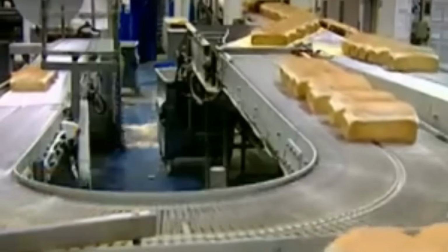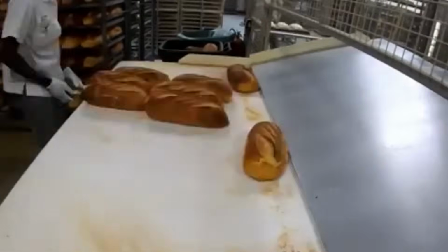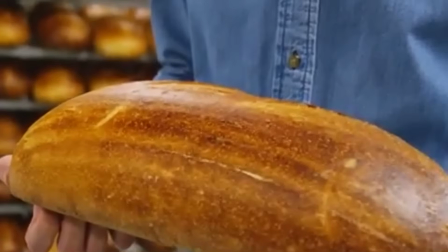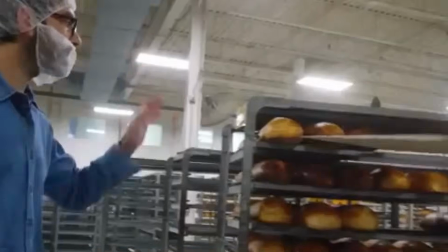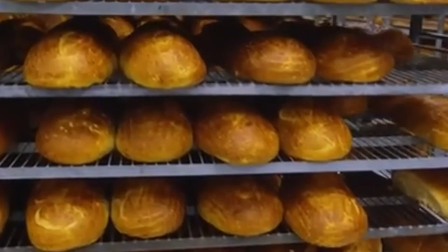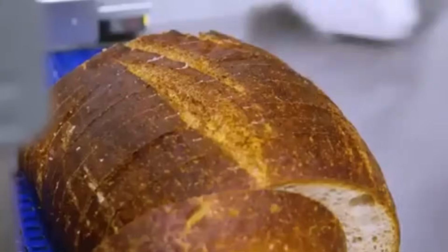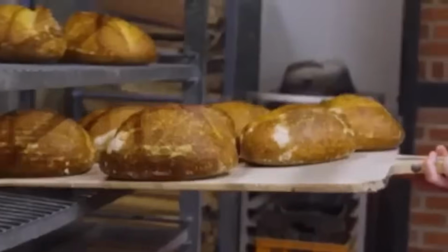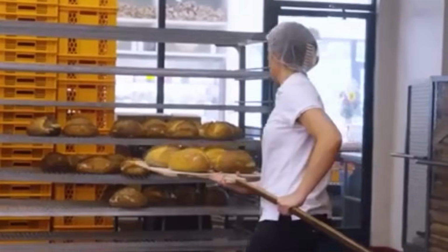Exiting the oven, the loaves are hot and fragrant, but far too fragile for packaging. They roll forward on the conveyor and enter a spiral cooling system, a towering structure of coiled belts that winds upward, allowing the loaves to circulate through cooler air over the course of 30 to 40 minutes. Fans direct airflow from multiple angles, and vents above the line extract excess humidity to avoid condensation forming on the crust. As the temperature gradually drops, the crumb sets fully and moisture redistributes inside the loaf, ensuring softness remains throughout shelf life. Once cooled, the pans reach the depanning machine.